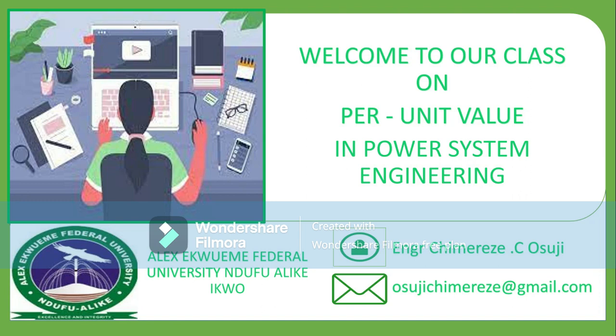And also in per unit here, we are going to be seeing how a transformer can be replaced with a reactance, thereby reducing the entire circuit to a simple single line circuit without transformers here and there, thereby simplifying our analysis of the circuit. So now let's get into class and look at the per unit value.